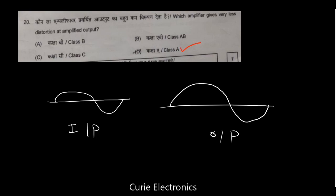In the class A amplifier, maximum efficiency is 25%. Okay. Maximum efficiency is 25%. But it can be increased up to 50% by transformer coupling. That you should remember. It can be increased up to 50%.